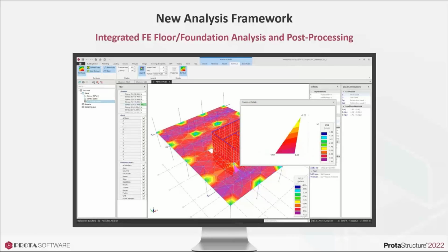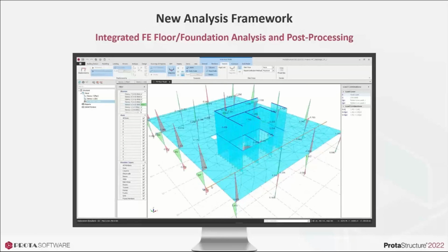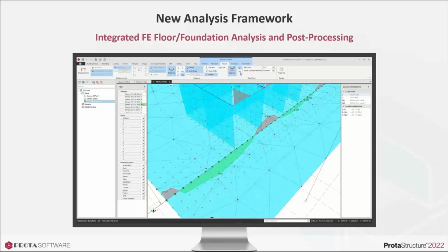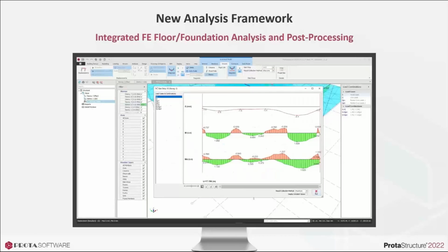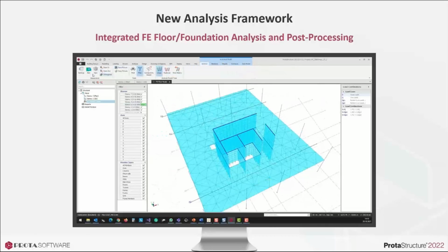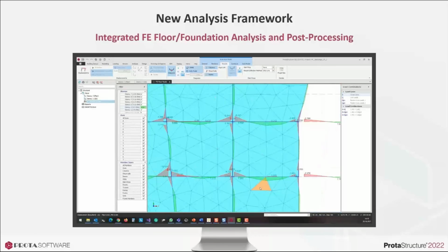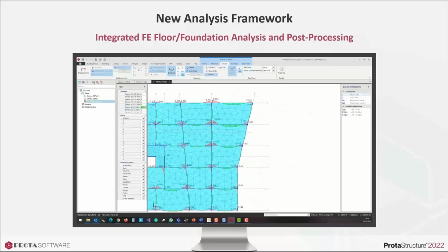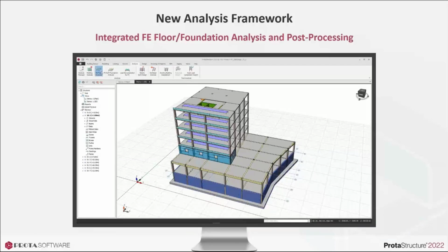And also, we have a special plan view for diagrams, as you saw in this short video playing on the screen. You see here the 3D slab strip diagrams collecting results from the station points. And also you see the detailed profile on the screen. You see here the special plan view diagrams. When you switch to plan view, the diagrams are also translated to the plan view counterparts.